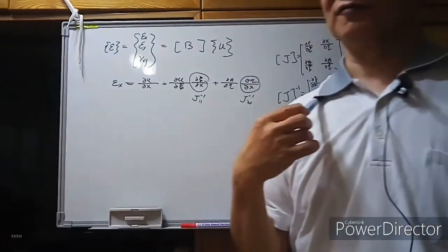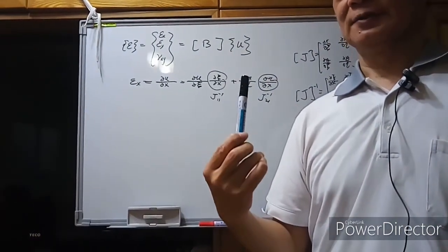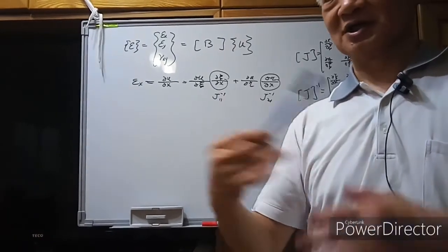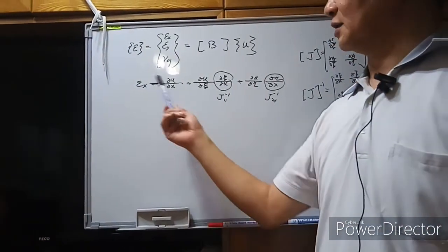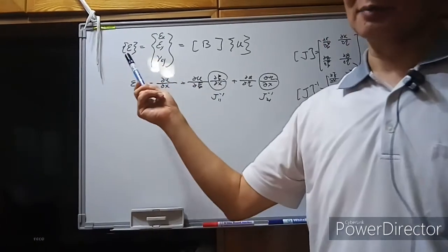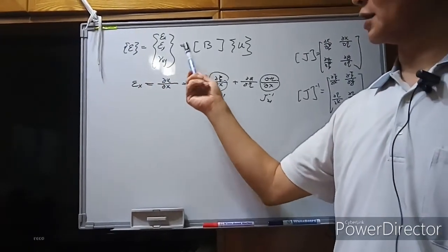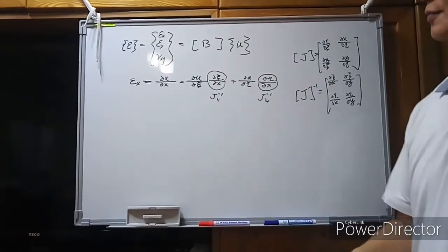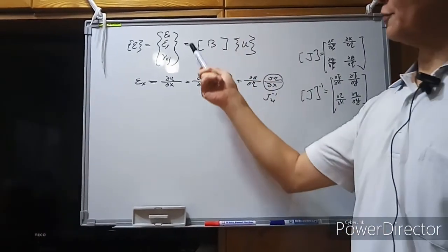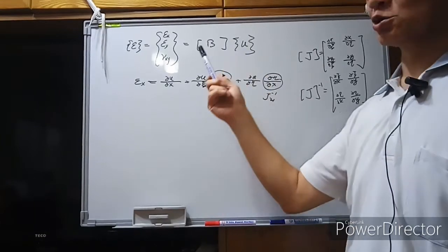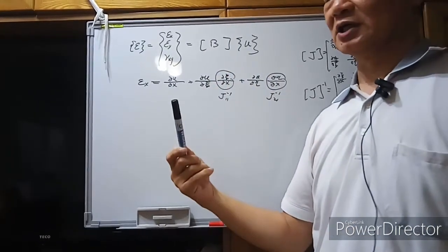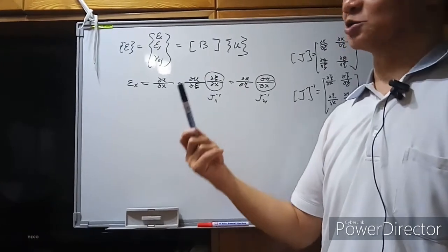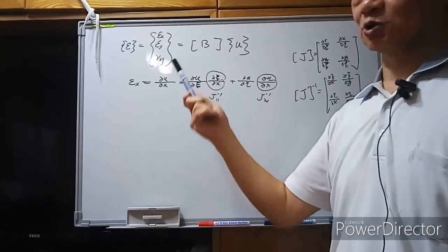And all these will not be changed since the description of the UV functions and the derived phi functions are usually exactly the same. The solution procedure for epsilon x, epsilon y, and gamma xy is also the same. So for both problems we use the same procedure to calculate the B matrix.